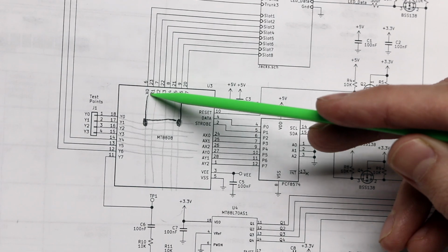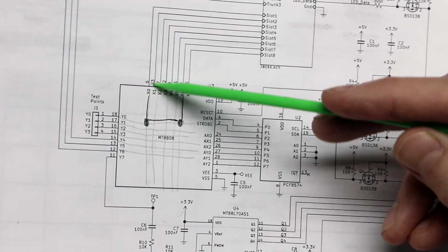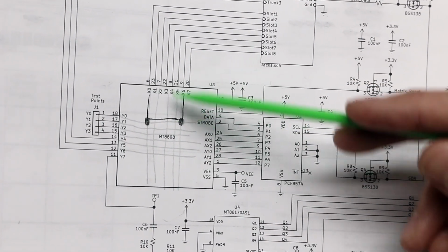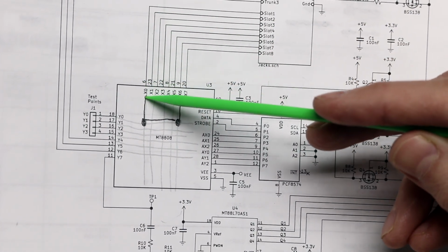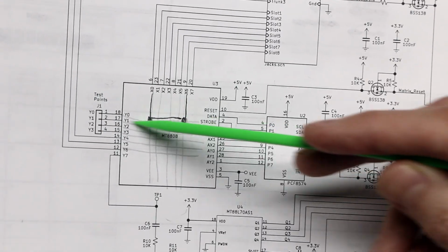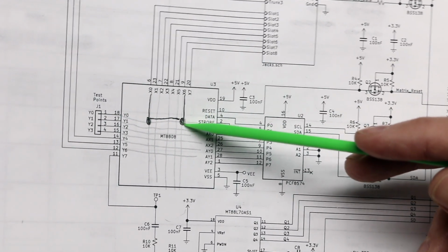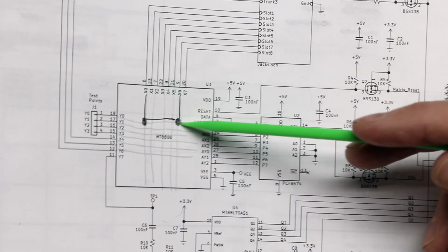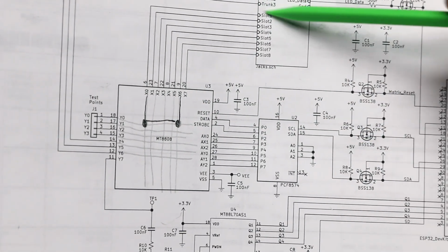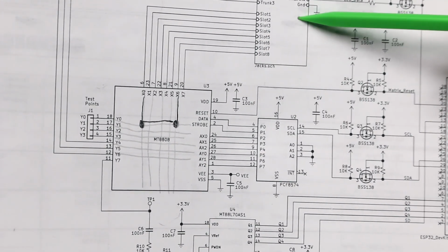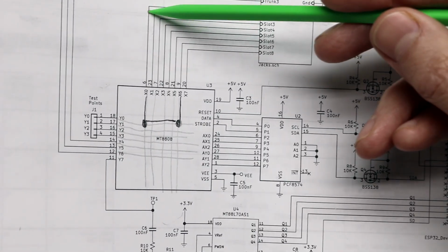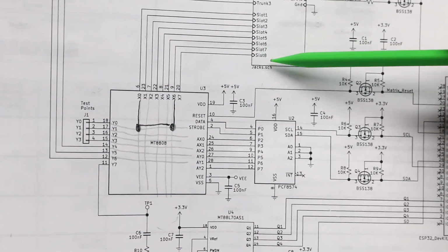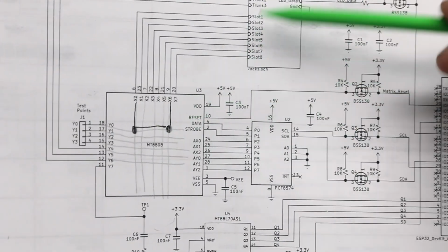So I've drawn in on X0, we connected the node at X0 and Y0. We also connected the node at X6 and Y0. So what we're doing is creating a path from a signal on X0, getting down to Y0, and then it's on this horizontal line. Then we close another switch here, making contact with this vertical X6 line. So we have a circuit path going from X0 to X6. And that would represent phone jack connections on that circuit board. So a phone cable plugged in here has analog audio able to pass through and come out to the other one here. Of course, it's a two-way audio path.